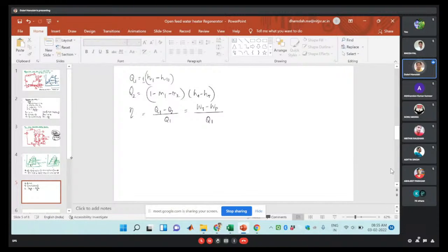Okay, so the steam rate formula is the ratio of 3600 upon WT minus WP, right? So that is the steam rate. So in this case, if we correlate the mean temperature of heat addition without regeneration with regeneration, it will be Tm1 with regeneration. How much will it be in this case?